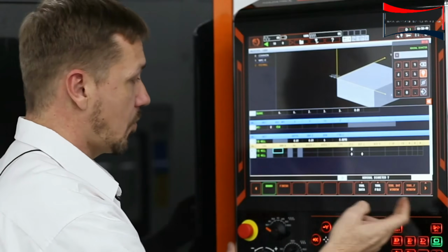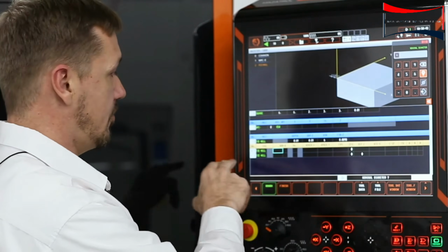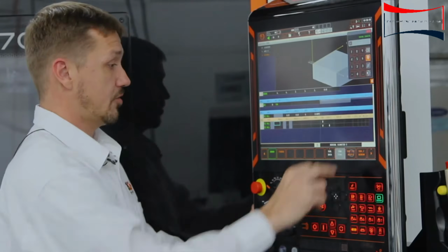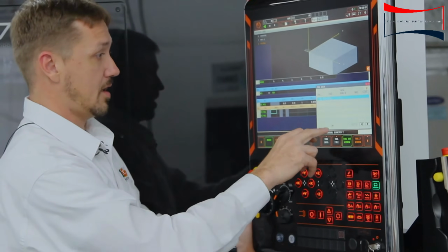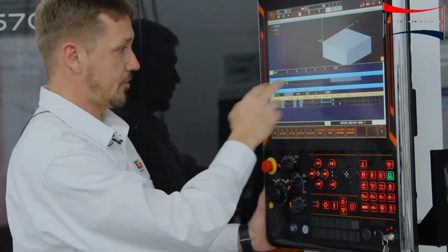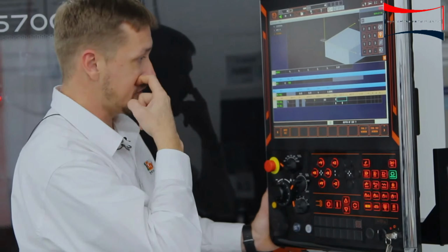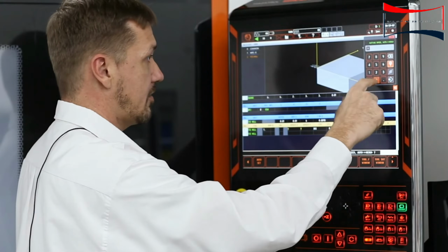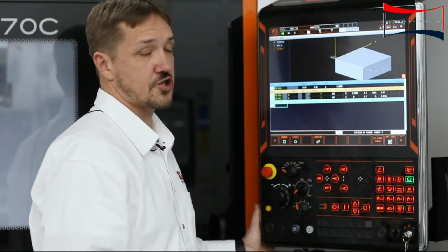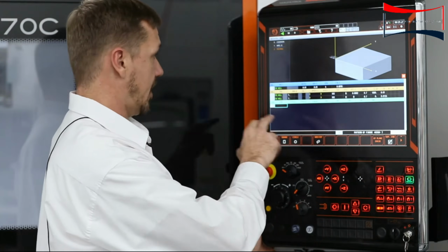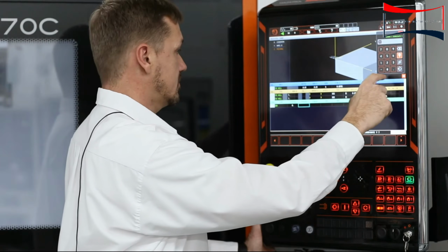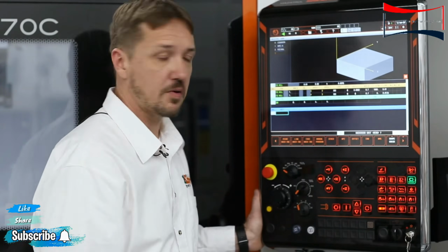So now, we know what kind of process we want to use. Now what kind of tool do we want to use to do it? Again, question and answer. So we look up our tool data. We've got a 1 inch face mill there. We'll just auto set all of that according to the type of material it is. We'll set a cutting speed of 1,000 and a feed rate of 10. And now I'm into the shape I'm trying to machine. So in this case, I've got a square that starts off at 0, 0. So now we've just faced the top of our part.